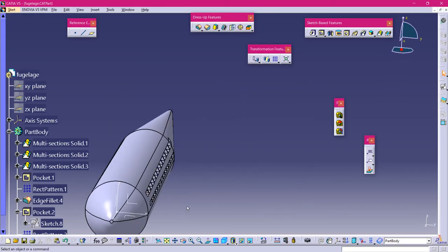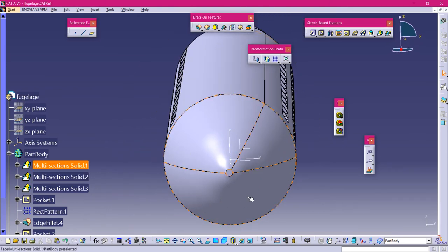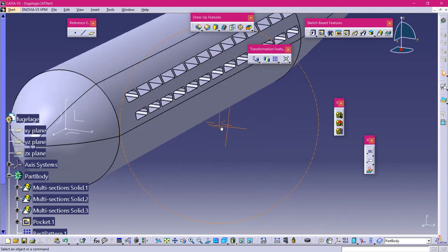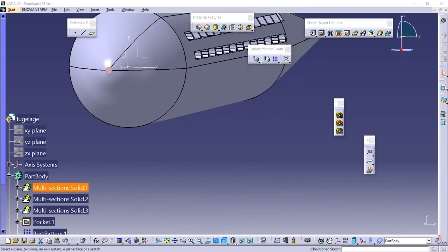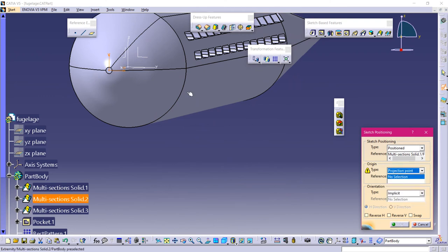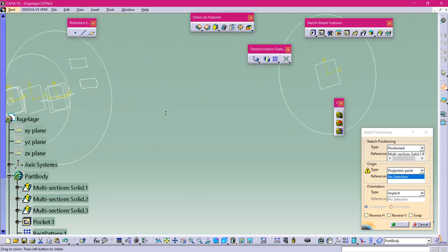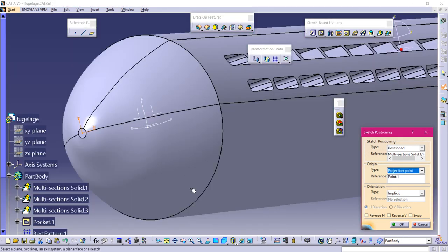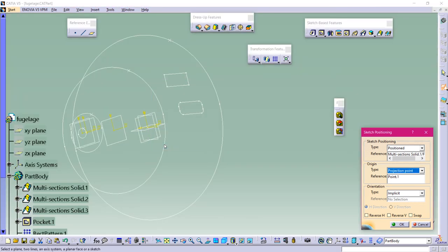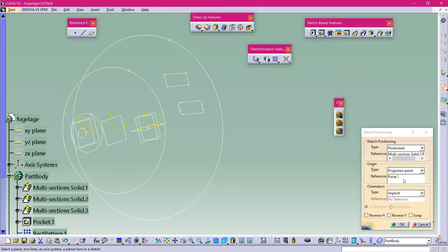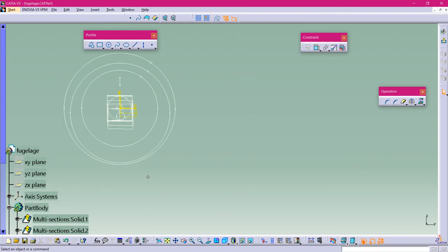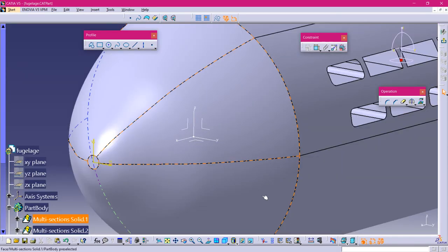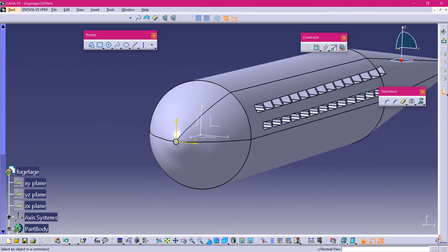Okay, now just see, our fuselage is almost ready, and now we have to create the pilot's cockpit, so we need a slot here also. What I'm doing is I'm selecting this plane, sketching, position sketch, projection point, somewhere is origin, need it. Okay, projection point, I selected the origin. First edit will be useful for us. And then I start sketching here.